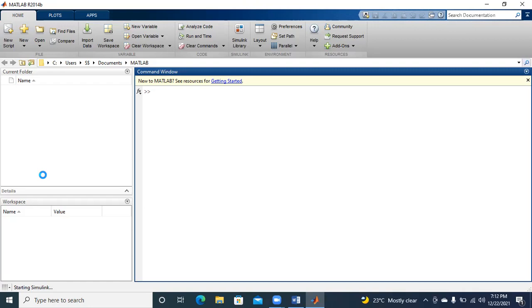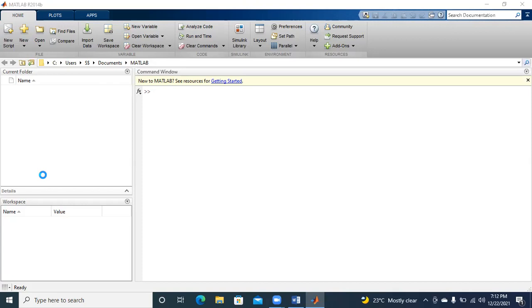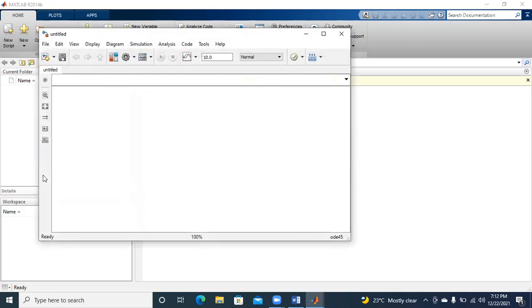Coming back to Thevenin's theorem, whatever the complicated network is, it is reduced to three elements. One is the load, which is already provided in your complicated network. The next one is your equivalent voltage source, and the third one is the equivalent impedance.